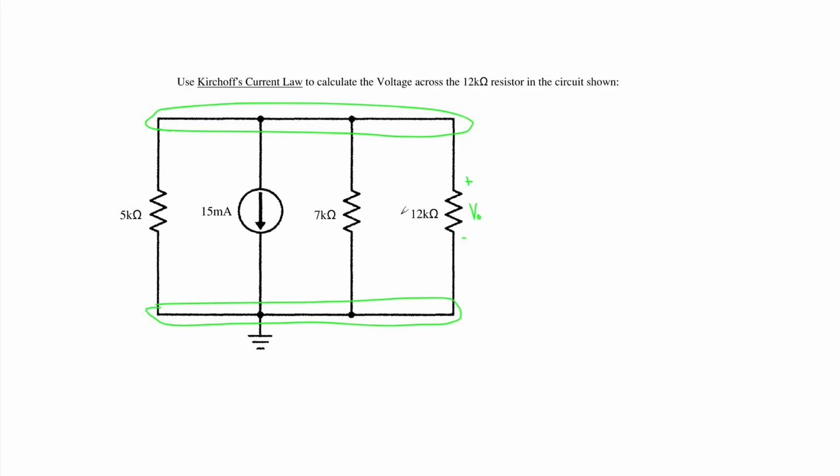So utilizing Kirchhoff's current law, we can recognize that our current at our source, we will denote as I1, is equal to the incoming currents of all three branches. And we will label this I2, I3, and I naught. So now that we've got some parameters and our values, let's go ahead and write our equations out. Starting with I1 is equal to I2 plus I3 plus I naught.